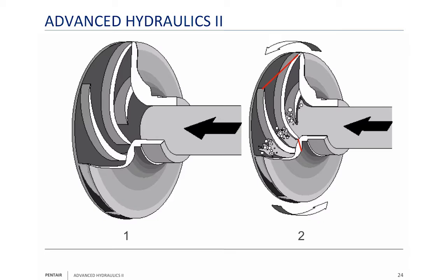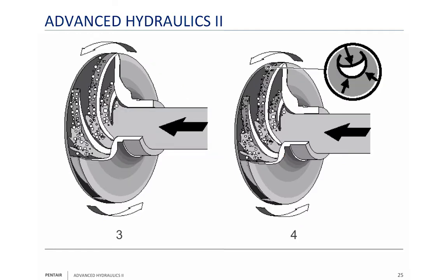And he's right. So what happens when the vapor bubble, now remember, this is cold water, this isn't hot water, gets out to the outside edge? We're going to push that water this way. Remember, we're trying to increase the velocity of the water. So as the water moves out in that direction, the vapor bubbles are going to move along with it till they get to a high pressure point and can no longer remain vapor.